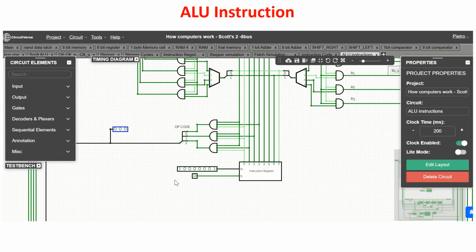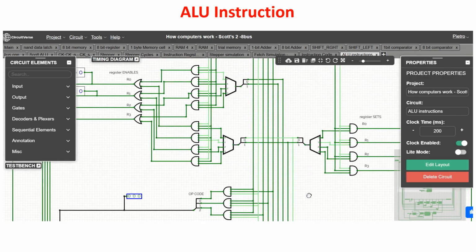So in our case we see our instruction code is an ALU instruction because the first bit is at 1. We have 000, so it is an add instruction, and we ask to add the content of register 0 to the content of register 1. So reg A is 0, reg B is 1, and so we have to put a result in reg 1. So we acquire this code.